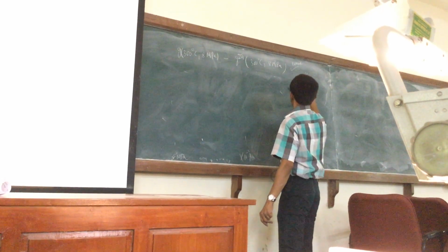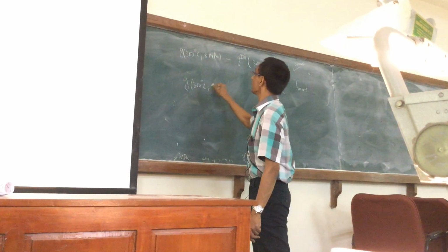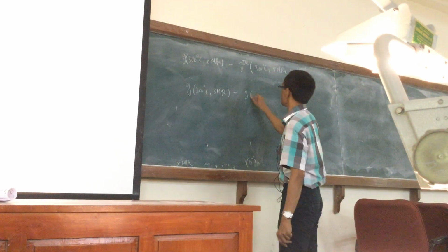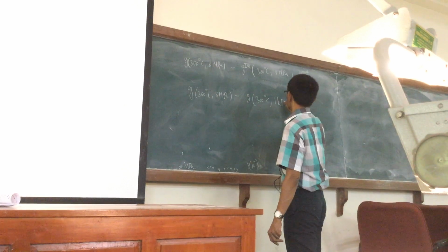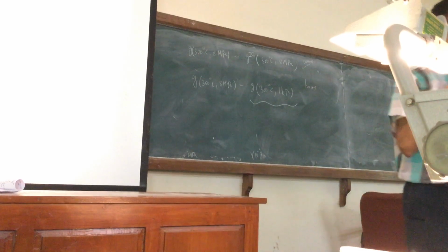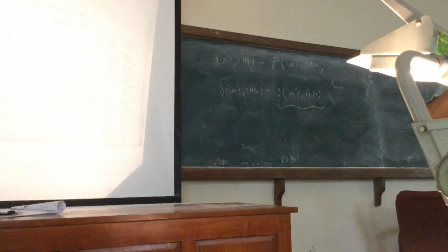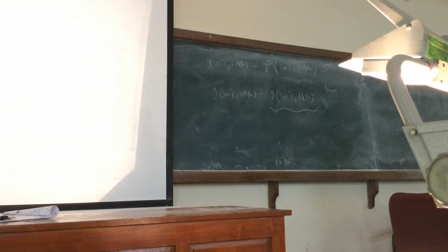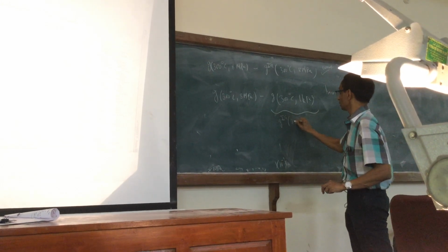What I have now so far from the calculations is G at 300 degrees centigrade, 8 megapascal, minus G at 300 degrees centigrade and 1 kilopascal. This is approximately the actual, because the table doesn't give the ideal gas values. However, this is a sufficiently low pressure, and I assume that the properties of the actual water will approximate its ideal gas properties. I can write this also as GIG.